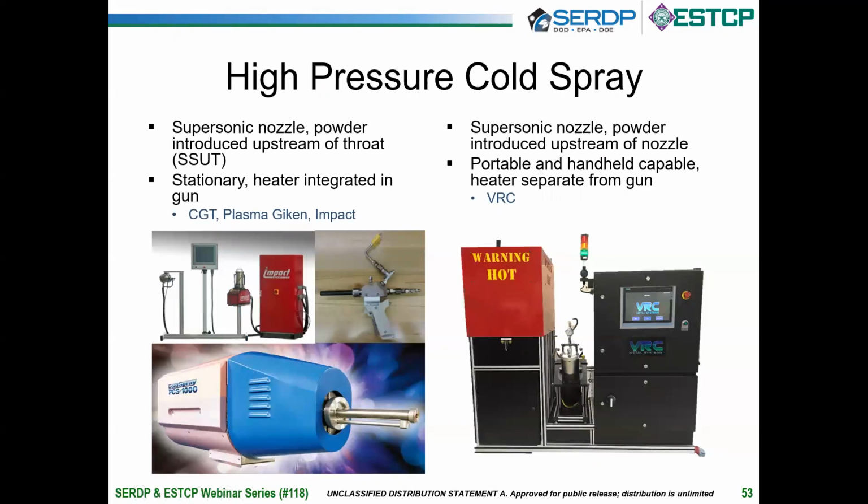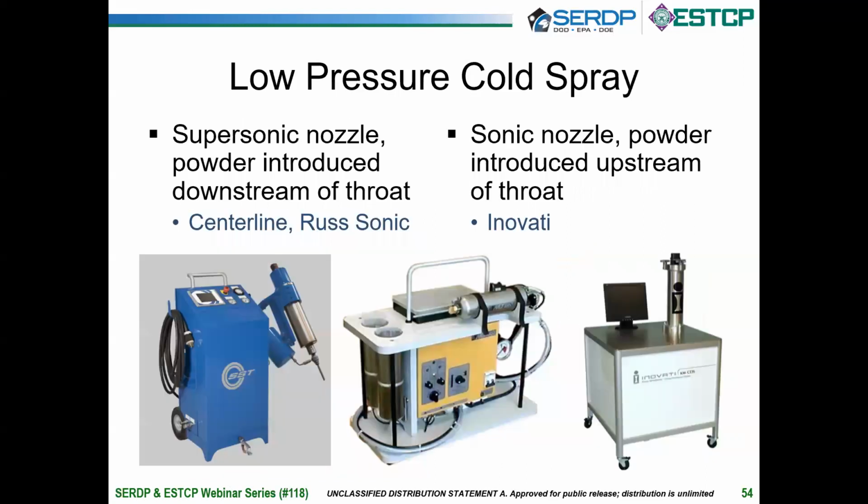All right, so now I'm going to talk about equipment. There's high pressure cold spray and low pressure cold spray. These are general categories. With high pressure, we're talking 100 to 1,000 PSI. With low pressure, we're talking about maybe 50 to 250, depending on the system. These are some of the low pressure systems.